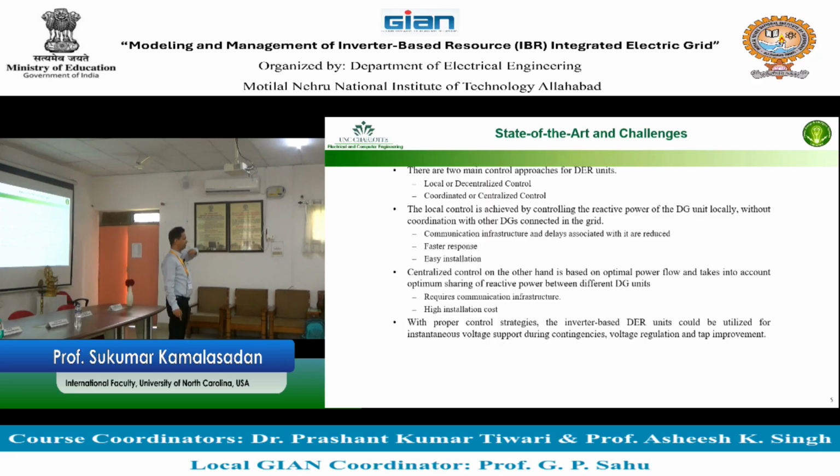What is the difference between hierarchical control and centralized control? You have a level of hierarchy, which means central will give something to the area. Area will give something to the local, and local will react on it and give feedback to the area. Area will give feedback to the central. Central will say, "Oh yeah, that is good," or "No, change this." So this is hierarchical. You are doing it in a hierarchy form, right? This hierarchical form is coordinated because you are coordinating every level of devices. What do you mean by local or decentralized?